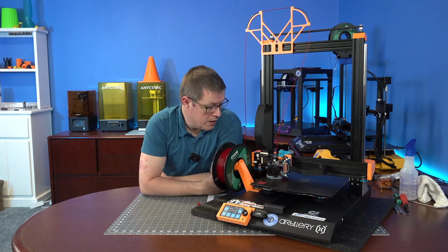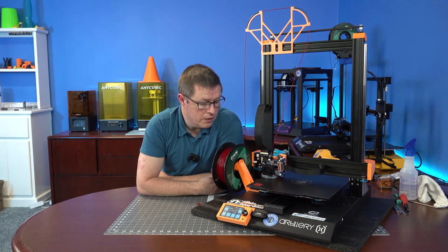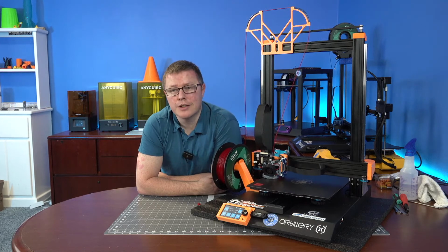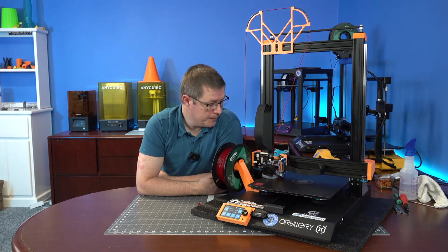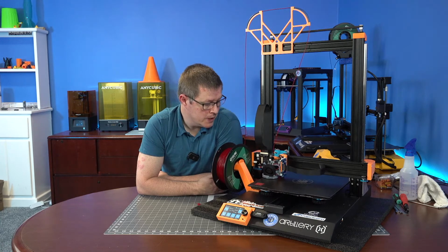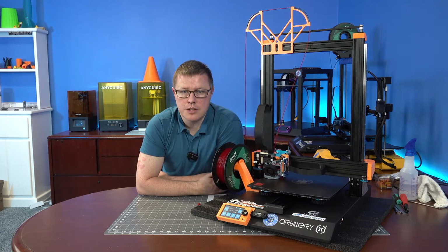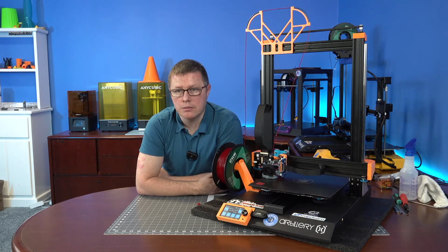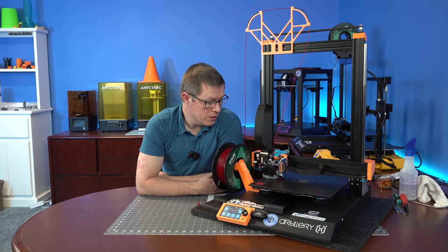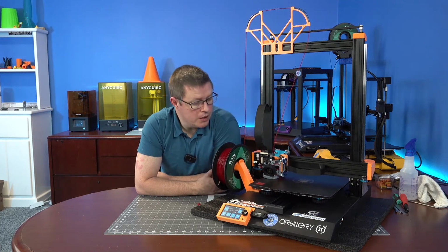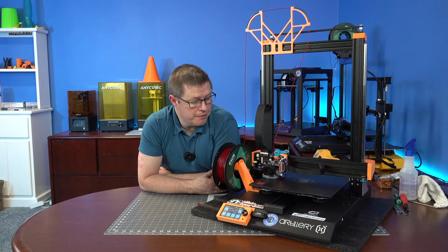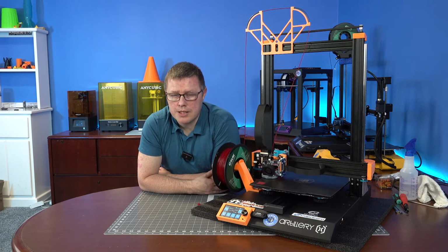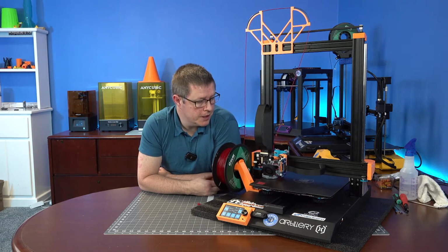All right. Yeah, it's way too close. It's funny. It's okay. That's why we do this. I think that feeler gauge I use is like 0.08 millimeter. It's a super thin feeler gauge. This is looking better. So this is about what is this, a 9-minute print, 10-minute print, it said in here.